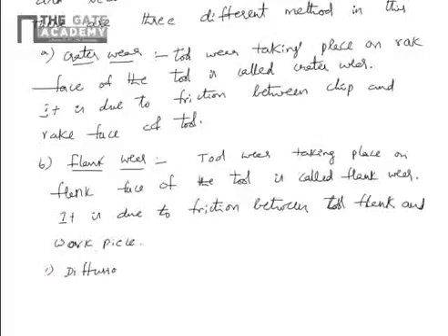Diffusion wear. During machining of ferrous workpieces using a diamond cutting tool, carbon atoms start diffusing from the diamond cutting tool to the workpiece because of the ability of the ferrous material to absorb carbon particles.